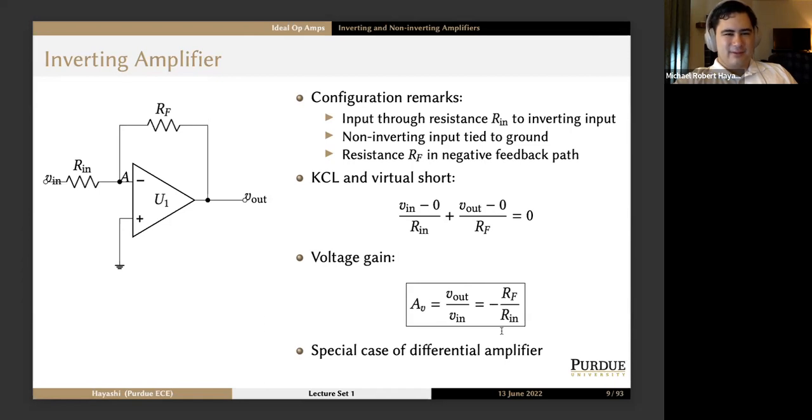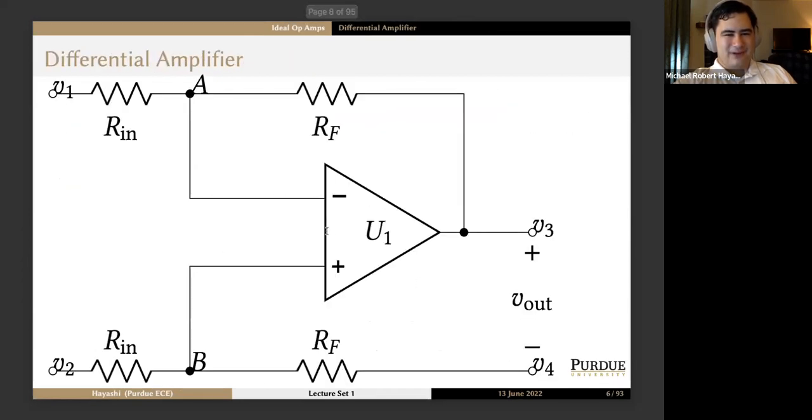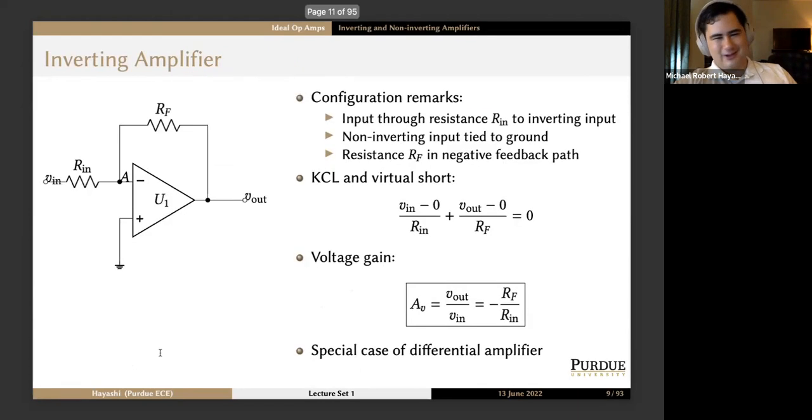And if you do a little bit of massaging to the differential amplifier, where you let the lower Rf feed forward resistance go to 0, and you let Rn also go to 0 and neglect the input, there's a whole bunch of changes you'd have to make. You could get this. However, I think it's easiest just to rederive it rather than treat it as a special case.